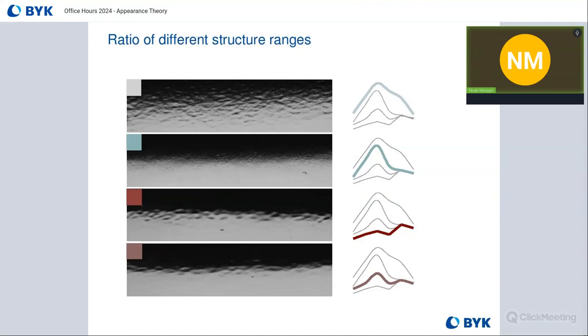So to recap, when we started, both short and long waves were high. So we optimized the clear coat to lower the WD and WE scale in their values. Then we had higher short waves, so the WA, WB, and WC were higher. So we sanded the primer to lower those values. And then we saw that we lowered the short waves too much and needed to increase the short waves to balance the spectrum. So we optimized the primer and the top coat. And that gave us our final image at the bottom there.